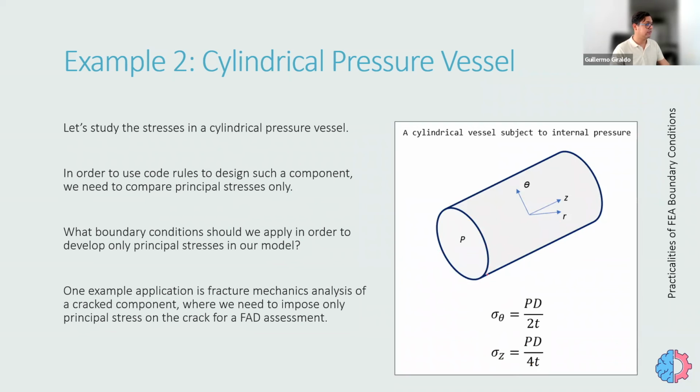This axial stress is created also by the internal pressure, but say that the end caps of the pressure vessel or the bendings, they create an axial stress, right?